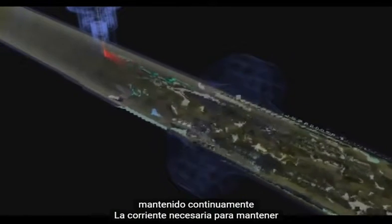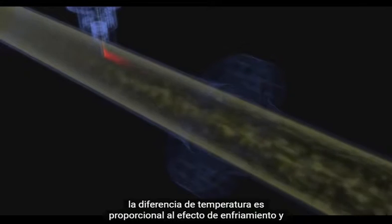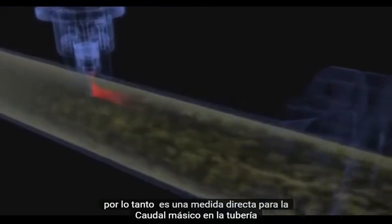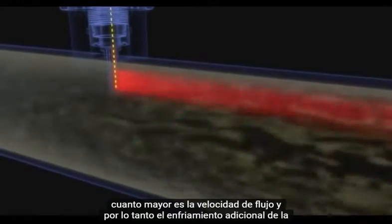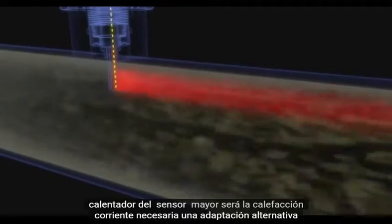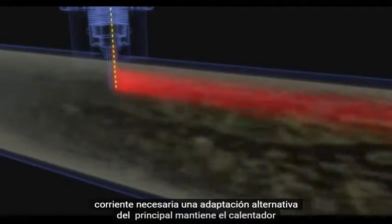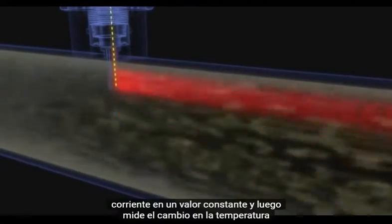The heating current required to maintain the temperature difference is proportional to the cooling effect, and therefore is a direct measure for the mass flow in the pipe. The greater the flow velocity, and therefore the additional cooling of the heater sensor, the greater the heating current required. An alternative adaptation of the principle keeps the heater current at a constant value, and then measures the change in temperature differential.